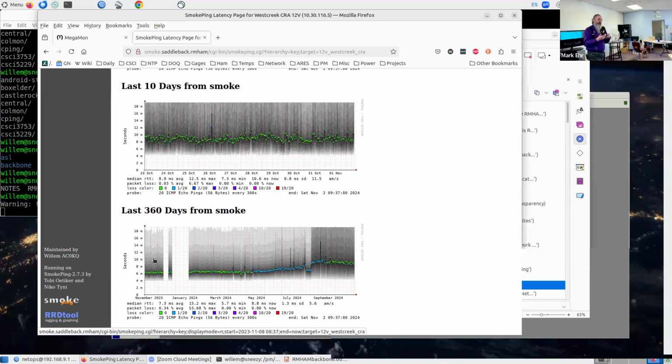So this is our workhorse router that we have at most of the sites. It's a MikroTik RB2011. Costs about $100, so it's not an expensive device. However, the signals that you get for IP are in the 1 or 2 volt range, right? So if lightning suddenly puts 50 or 100 volts into one of those ports, it does not survive. Fortunately, our experience with this kind of device is that it usually blows out the port itself, but not the entire device. So as long as it's a single strike, that's not too bad.